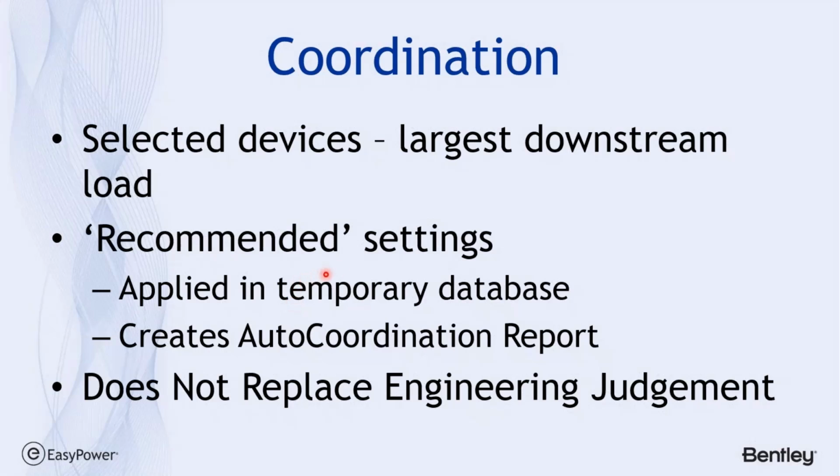I do want to emphasize that the function of auto coordination is not a substitute for engineering judgment. The intent is to make the engineer's time more valuable in the process, and many people would utilize SmartPDC as a first pass on what options are available for doing coordination, or as the last pass to make sure we haven't violated any rules that we're trying to follow once we've done the coordination manually.